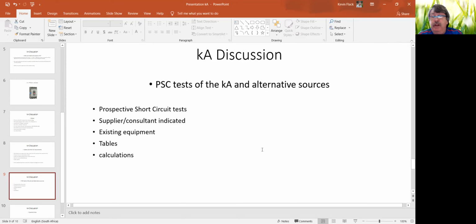We could really look at existing equipment. If you're going to a domestic house and everything looks right, and the minimum is in terms of those 2.5 or 3 kA, depending which spec you're looking at, and you replace it with that, the risk can't be that much worse than what it is. I think in today's modern areas where I would be more worried is some of the townhouse complexes, which generally could be above the older levels of that.